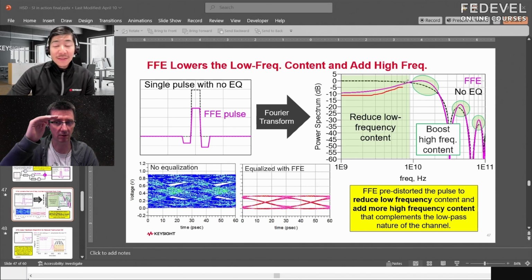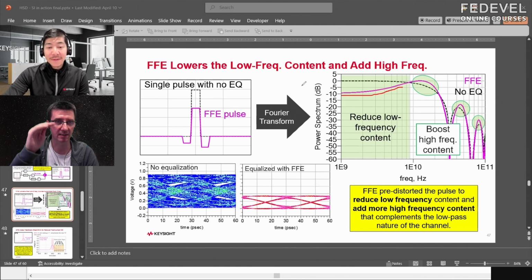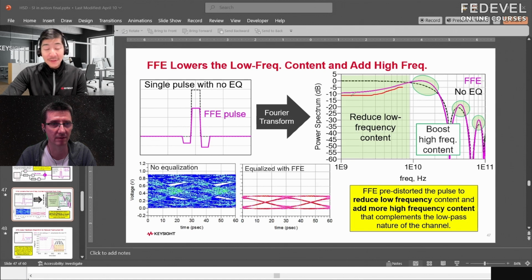Yeah, because equalizing, the top of the signal is a little bit lower, so the lowest frequencies need to be smaller. Right. Yep. Oh, and here's another observation. Since you have different tap values, it's trying to keep the TX the same. You're using the same TX power, so the tap values are restricted so that you're not using too much power. Interesting.